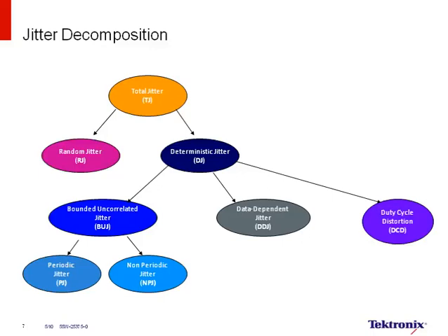So commonly, to be able to reduce RJ, you want to be able to look at things like your crystal oscillator. That's one of the causes of RJ. You want to look at the chips, the silicon that's used in your PLL design. That would be a cause of RJ. So when you think of RJ, one of the larger contributors is silicon. Can you put a different piece of silicon in there to be able to do that?